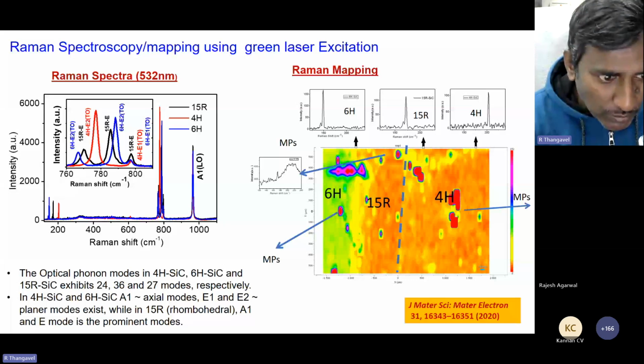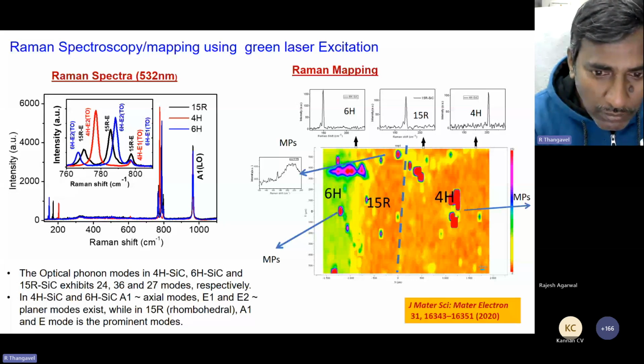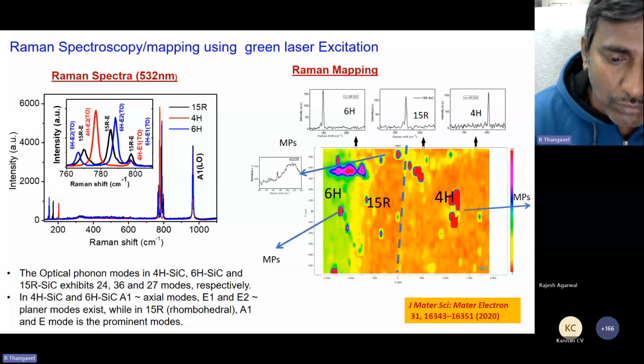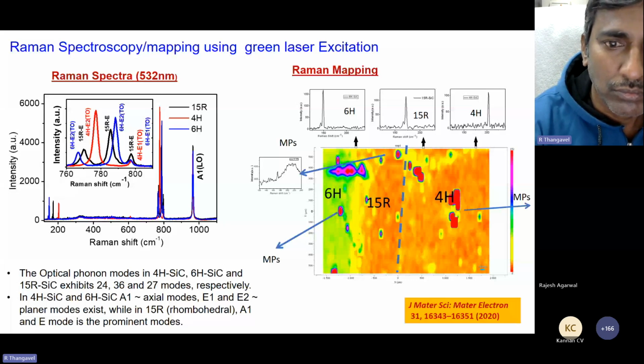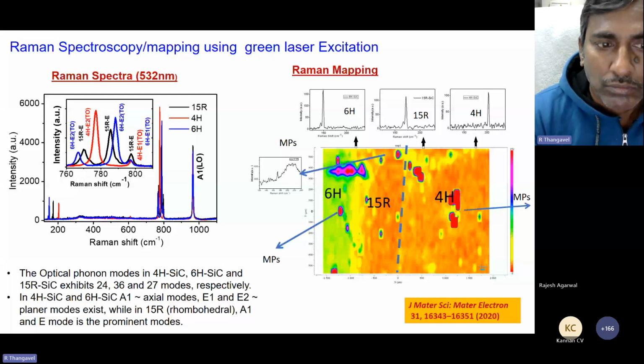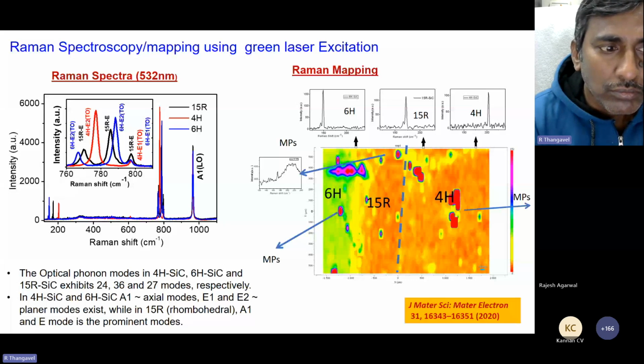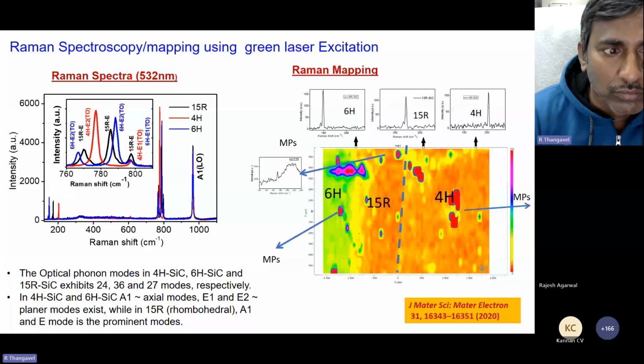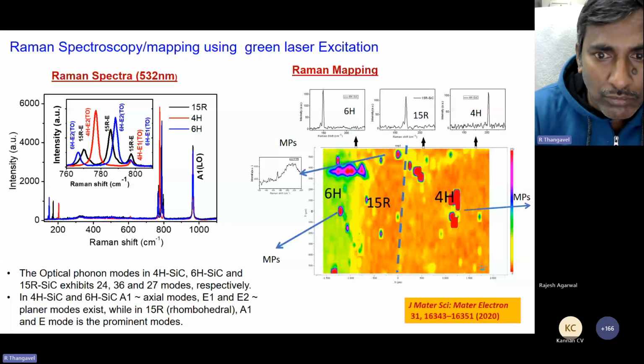So suppose we are making a PN junction diode, we have an N-type substrate, so to make it P-type, ion implantation can be done. Then ion implantation, then annealing. After annealing, activation annealing, then planarization. Then chemomechanical polishing will be there to make the surface planar. Then flip chip bonding, wire bonding, then testing and assembly. These are the common fabrication processing steps which have to be involved while fabricating the final devices.